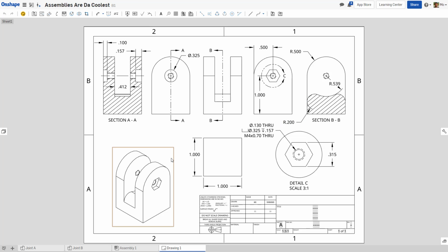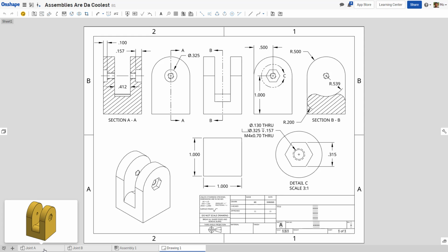When I return back to my drawing, I notice that despite having updated the text, the fields haven't been populated. That's because any time I edit a part that's represented in a drawing, the drawing will not automatically update until I've manually updated the drawing using the Update from this workspace tool. Clicking this will update my drawing, including the metadata, filling in the text for Title I.